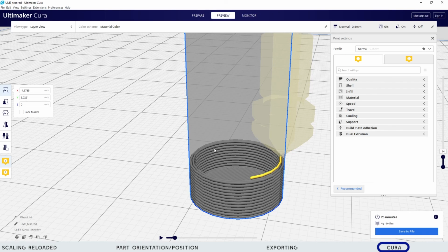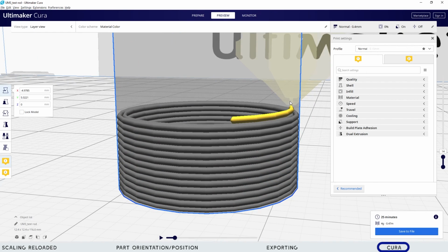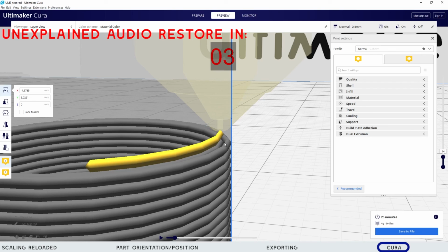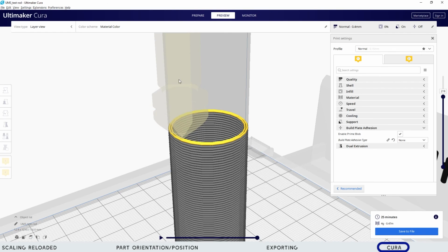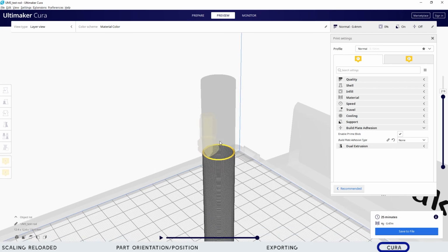So some little pieces of plastic might be sticking up, and the distance between the nozzle and this layer may not exactly be what's represented in the software. So this might actually be pressing up against the previous layer. There might be a larger gap. So the very fact that the print head is moving horizontally across here to lay down each bead of plastic, that motion is giving a horizontal push across, and that is multiplied the higher you get up on the part like this.